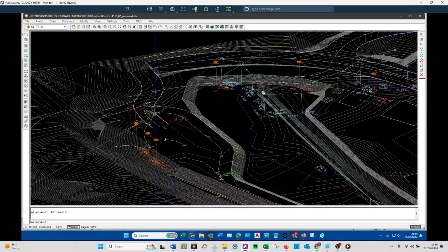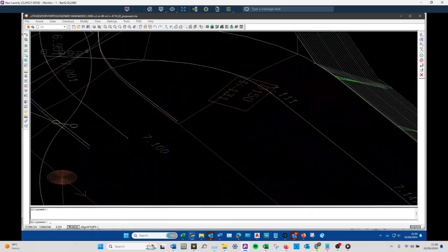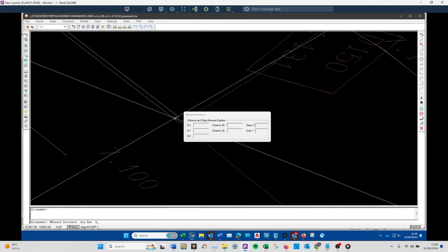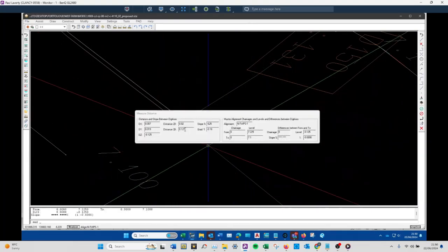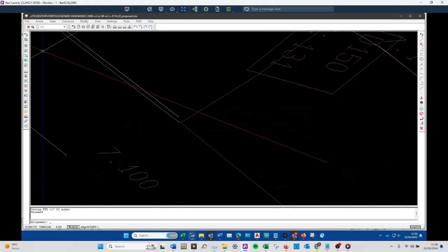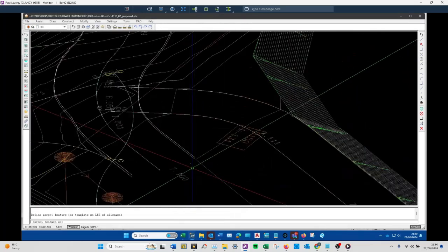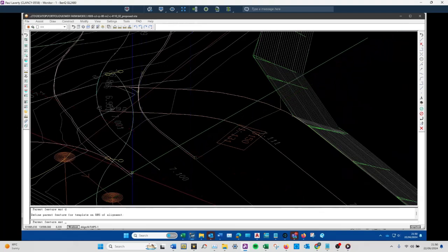And the other thing is the reason why I have this in the folder and also named to be at the top is because if you go back to this example that we have, there's 10 roads here. To insert all those templates onto those roads, you have 18 roads, 2 sides per that, so that's 36 at best. 18 times you have to go insert road template, and then it's going to have the drop down folder, and then you have to go and find it.